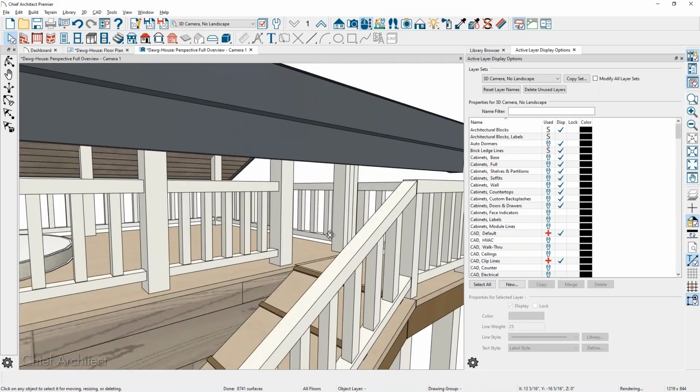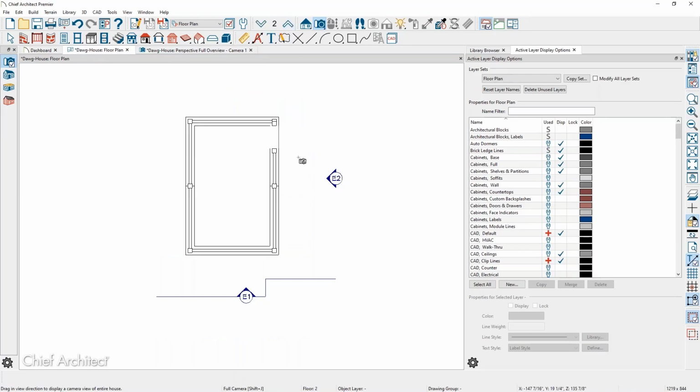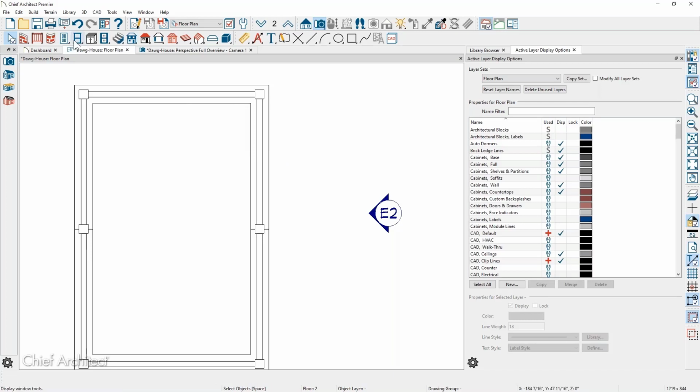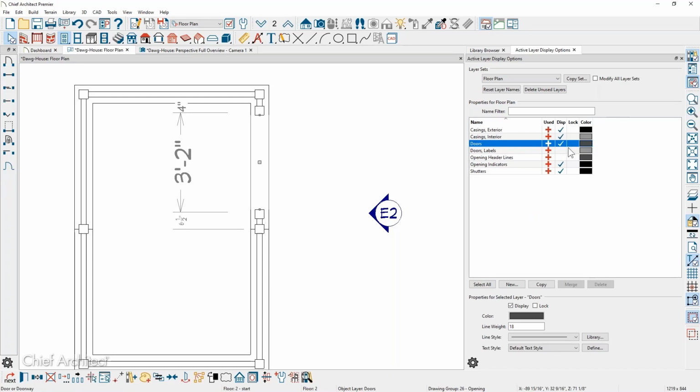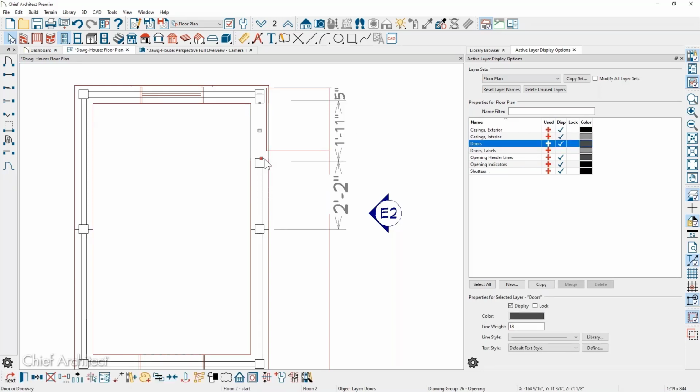But you see how we have the opening here for the access into the ramp and landing, and that's actually a doorway. And the way you place those doorways, you can see it in the floor plan view here. If I go ahead and delete that out of there, you'll find that tool underneath the door, and there's a specific tool called the doorway. And when you place this, let's make sure that layer is turned on so we can see it a little bit better. Yeah. So then all I did was slide that over, and if you press reference display, that will show you the floor below. Makes it easy to size that and pull it in right where you want to have that opening.